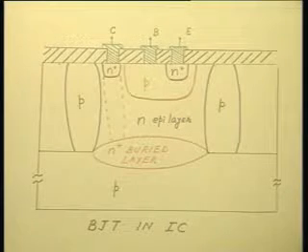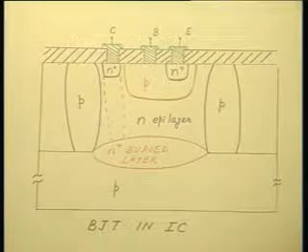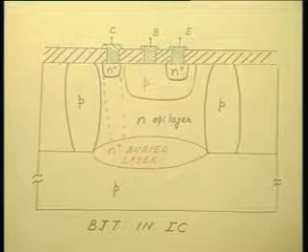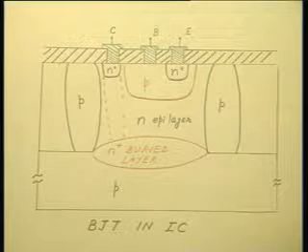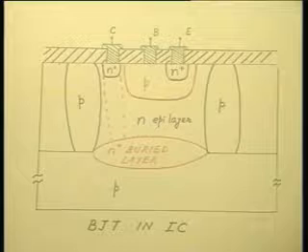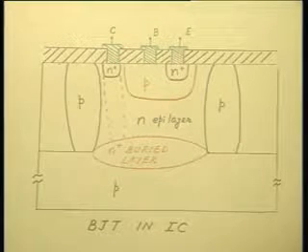We started with a p-type substrate. Normally we used 111 substrate. Remember, it is a comparatively older bipolar junction transistor. So, in those days still 111 substrate was considerably cheaper than 100 substrate, because now you know that it is much easier to grow 111 crystal, right. So, 111 substrate used to be much cheaper, that is why people started out with a 111 about 10 ohm centimeter